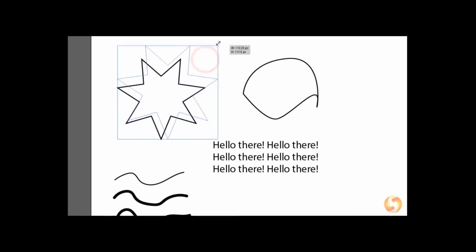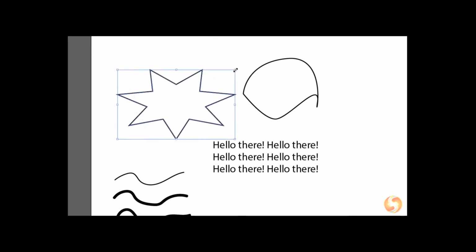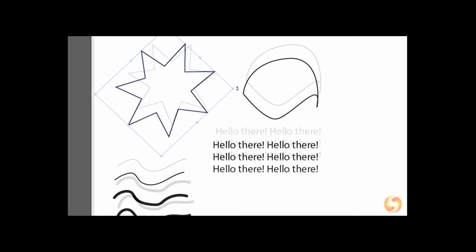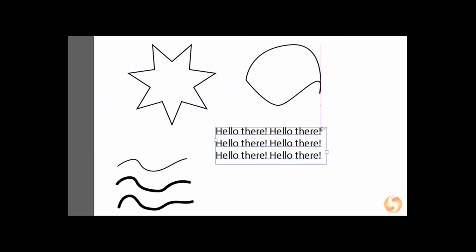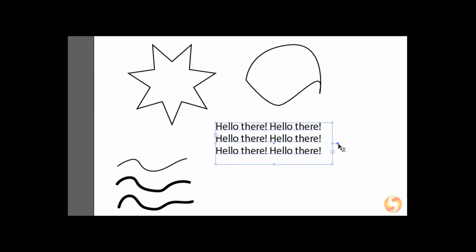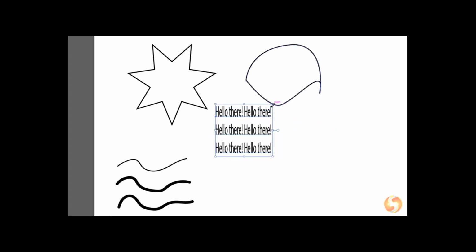With the Selection tool enabled, click and drag the skeleton to move the object. Use its white nodes to scale and drag from outside to rotate. When selecting any text box, you can size it to adjust the text distribution and also double-click on the blue node to resize text from its box directly.